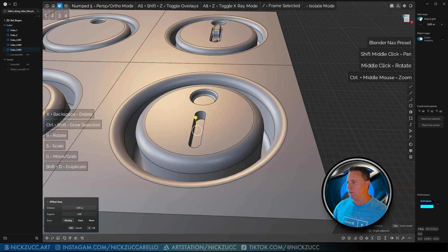And when I'm done, then I can take this face that we've got here, tap 3, and then I could do the match face, and then click this here like that, and hit OK. And then tap 2, like this, and then do a chamfer on there, like that. Right about there, somewhere in there. So that should give us everything that we're looking at for this feature here.